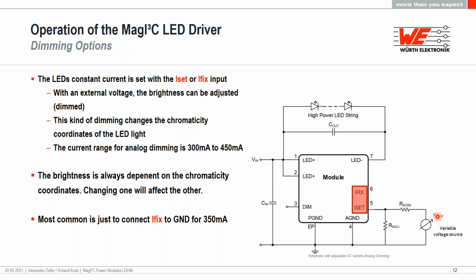This means from a digital analog converter, for example, the voltage here can be changed inside the application, also inside an already operating application, to change the LED current, to move the actual chromaticity coordinates to the requested coordinates, so that the color temperature is back to normal, like the circuit is new, like the LEDs are new.